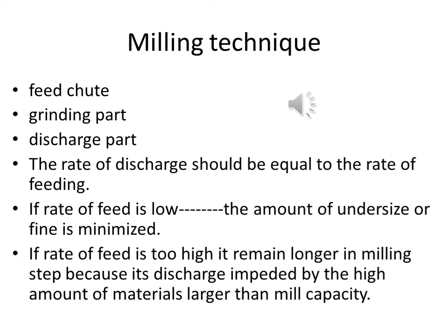If the feed rate is low, the amount of undersized or fine powder is minimized. If the rate of feed is too high, the material remains longer in the milling step because its discharge is impeded by a high amount of material larger than the mill capacity.